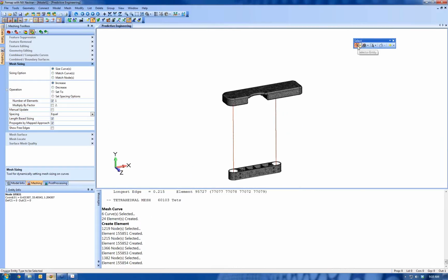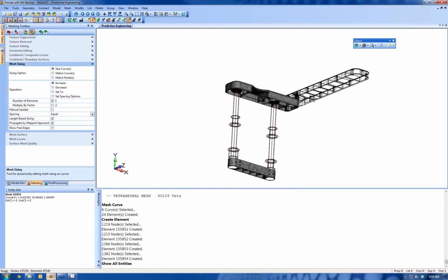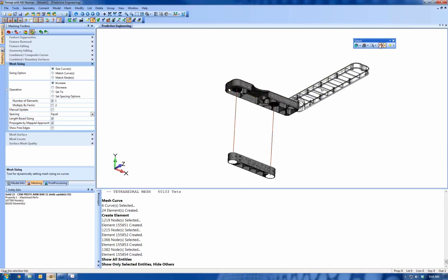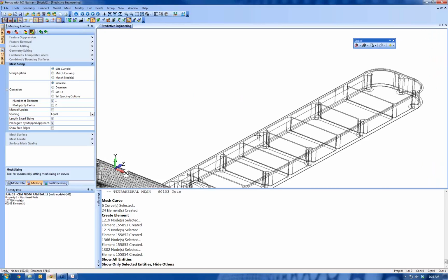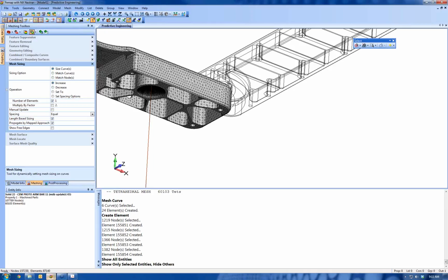So let's go ahead, back to our selector, turn on all our solids, and show everything. I want to use this solid and this solid. I'm going to show just those two because I'm not going to model this solid, but that's where my load gets applied. So I need this solid out here because there's a little point out here where I want to apply my load. And then I need this solid because that's where it connects in. So let's make one more rigid element.